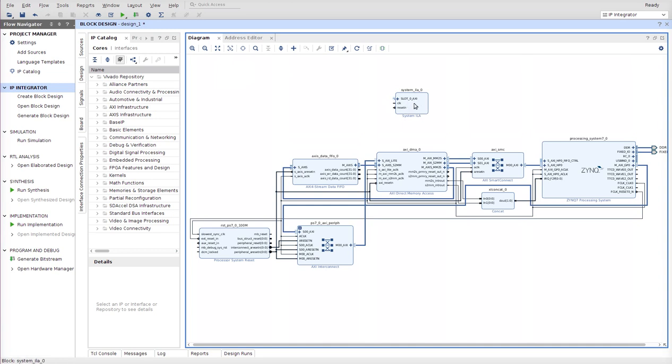So basically this is the block. What I'm trying to say is your FPGA is gonna have some extra logic just for this debugger. This is gonna be like a mini server that is gonna be collecting the buses or the signals that you want to watch, and then it's gonna deliver to you in the Vivado.